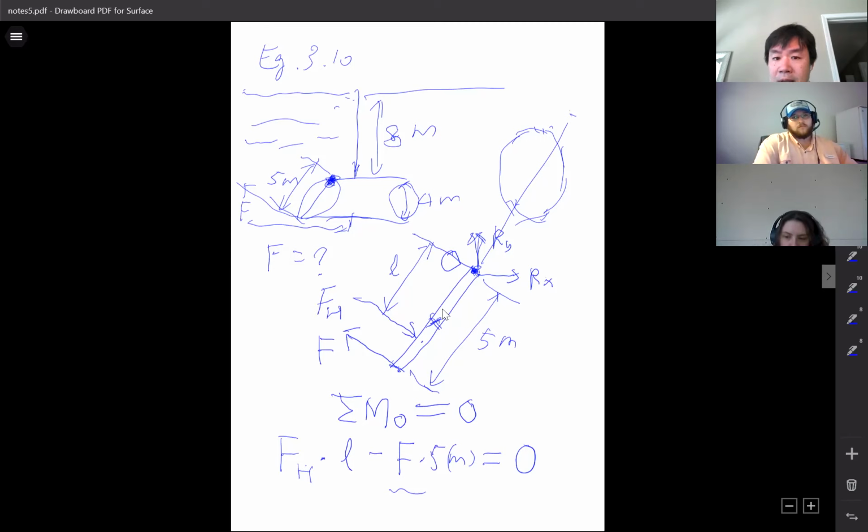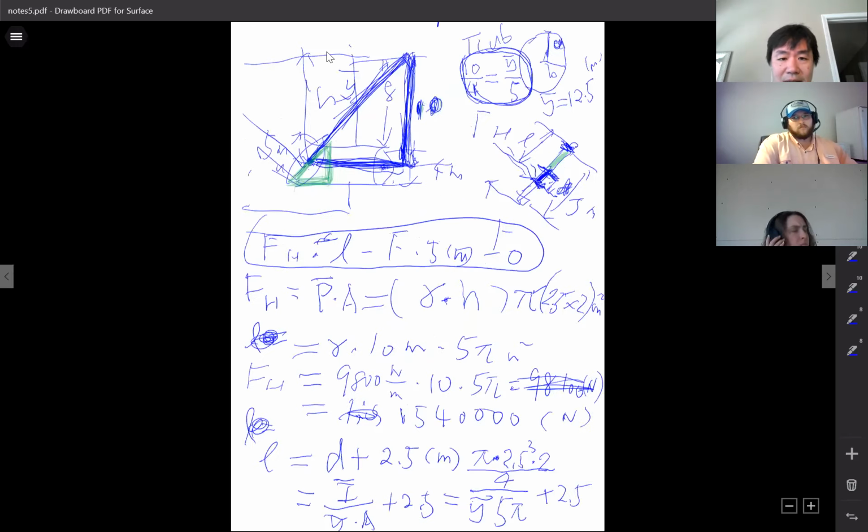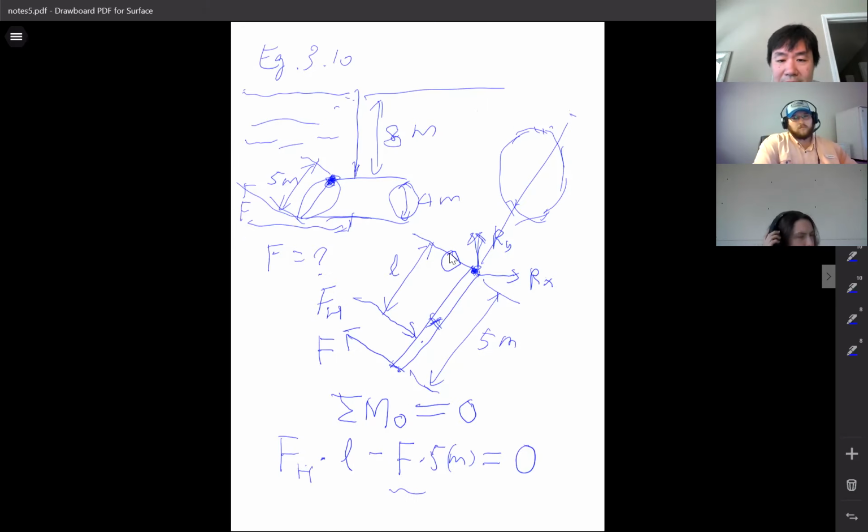Okay, so just keep in mind, in this type of problem, you need to understand a little bit of the geometry. For a shape, you need to know where the centroid is in terms of the coordinates, right? Then you need to know how to measure the water depth on top of the centroid. Sometimes, just like this problem, you need to use a little bit of geometry, right? Then that's it. Gamma times the water depth at the centroid, that's the average pressure, okay? Then times area.